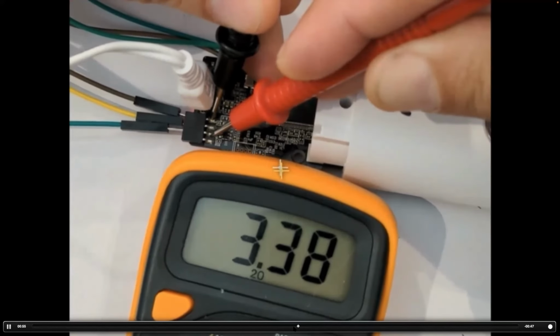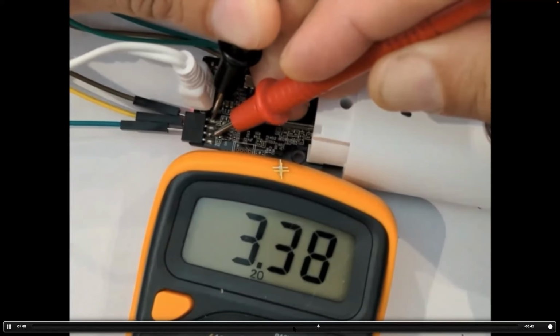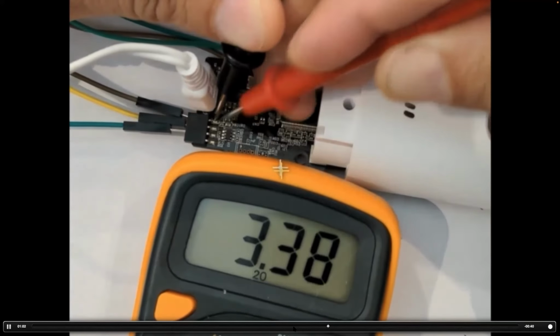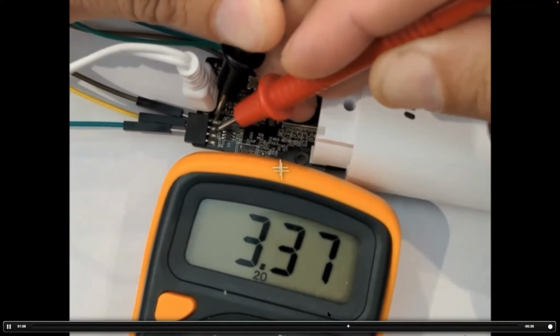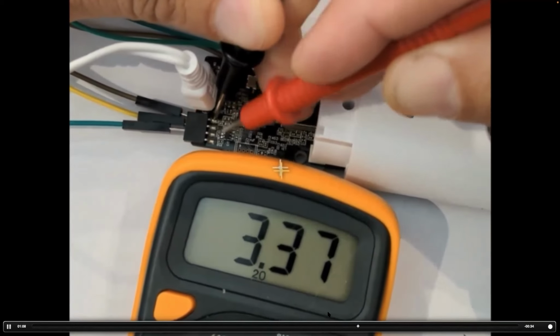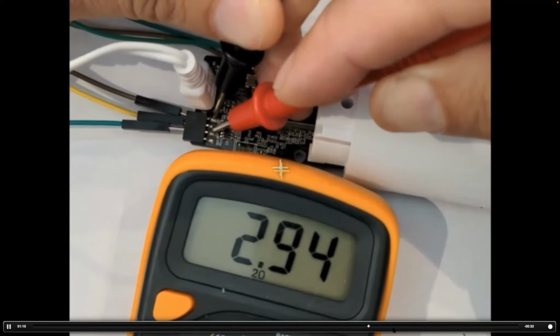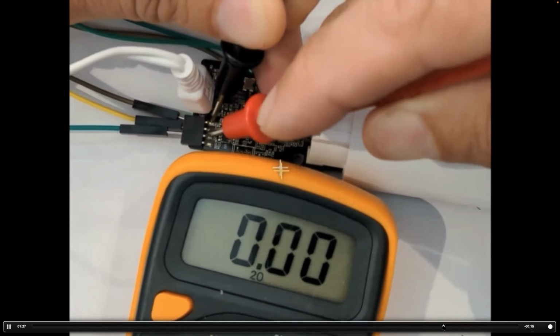For the transmit pin, as soon as the device boots up, there would be a lot of boot up logs or boot up messages that would cause a lot of voltage fluctuation in the multimeter. That voltage fluctuation will be very minimal when it comes to RX. And that is one way of identifying TX and RX on a UART interface. There are other ways as well, where you could use something like a JTAGulator or a logic sniffer to immediately identify what is the TX and RX.